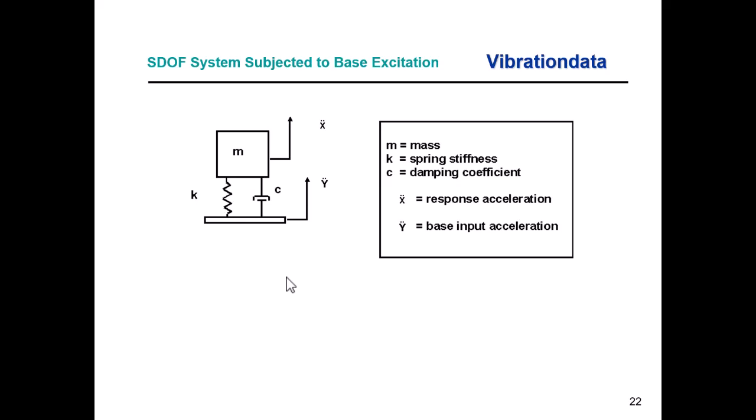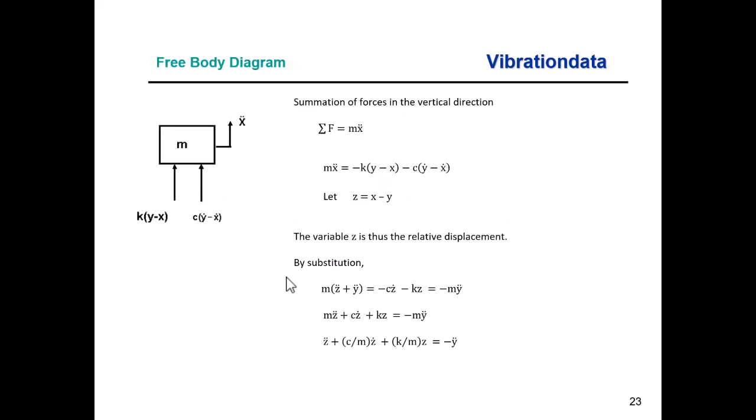So we need to derive a governing equation of motion, and we're going to go back to Engineering 101 and use a free body diagram. Now there's a couple other ways, energy methods and so on, but let's just keep this very simple, and we're just going to use a free body diagram. So it's interesting, this mass, there is no direct force on the mass, but there are two indirect forces, or you can call them transmitted forces.